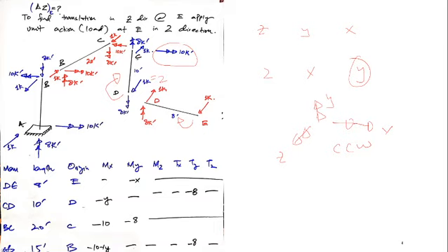Okay, balancing this joint C, 8 kip-foot would be balanced with 8 kip-foot. Upward, downward means counterclockwise, clockwise. 10 kip-foot counterclockwise is balanced with clockwise. 1 kip with 1 kip. Next, no loading here. This member has to be balanced in terms of moments, in terms of loads. 8 kip-foot and upward 8 kip-foot. 10 kip-foot is clockwise, so I have applied a counterclockwise here. This is 1 kip, this is 1 kip.